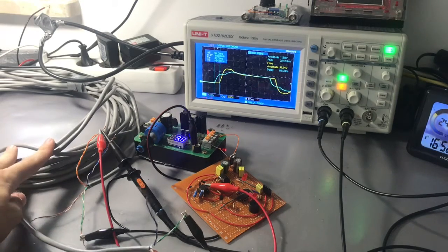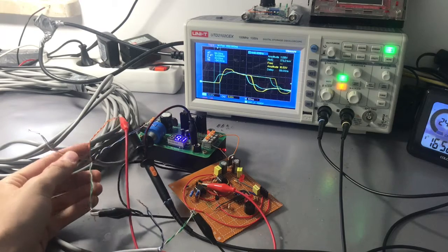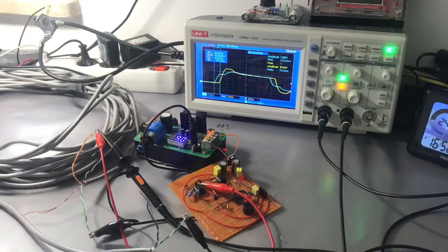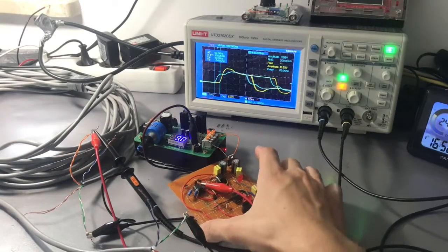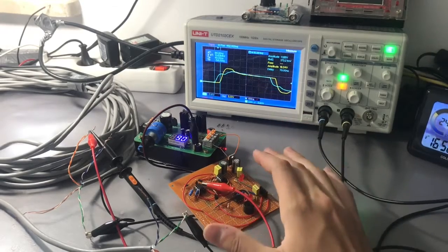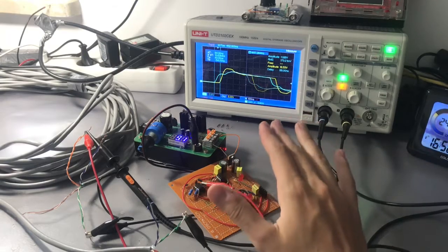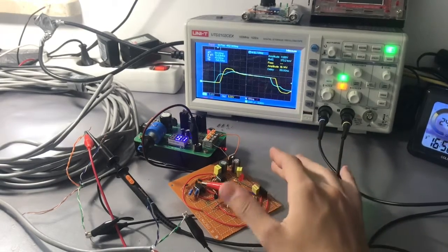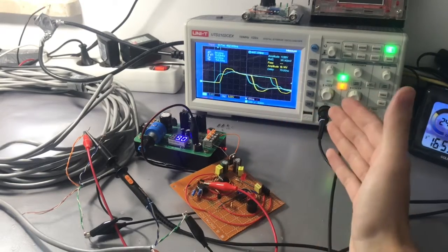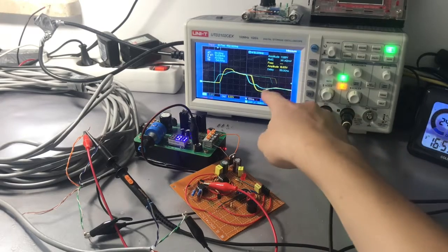So here we have a Cat5e wire, and as you can see it has 4 pairs of 2. I have twisted those pairs together here, and here I have a small circuit that will be in another video, but it's basically a 1 microsecond pulse generator, because this is the highest and fastest pulse that you can make with a 555 timer. It is, for example, useful for the HC-SR04 sonic distance sensor. So here you see the pulse.